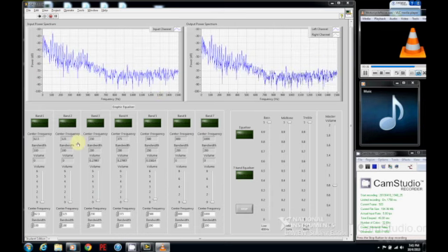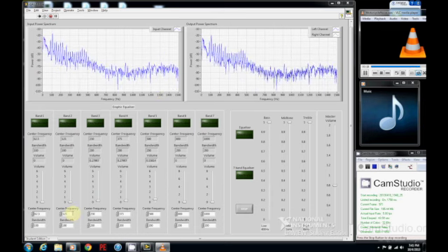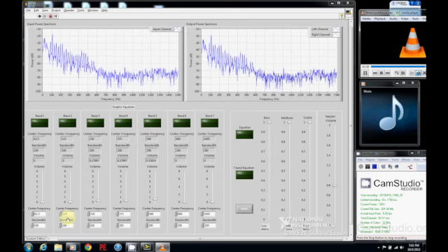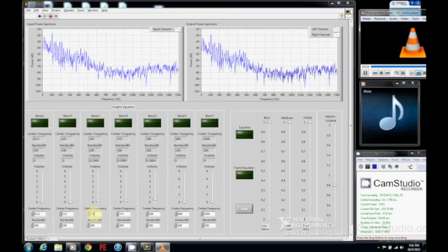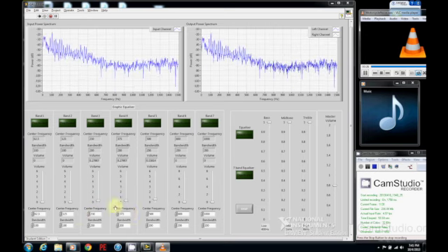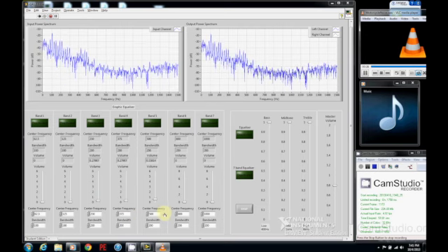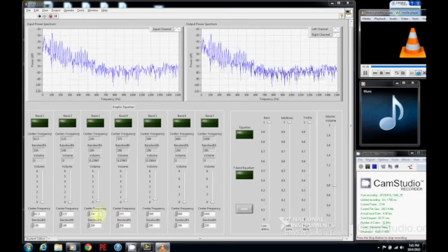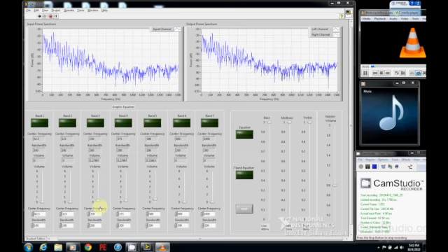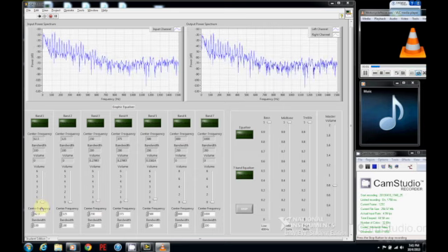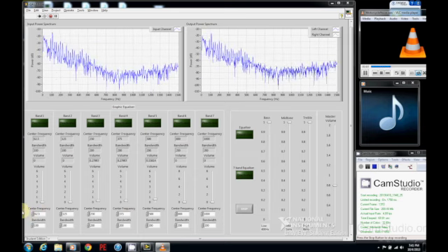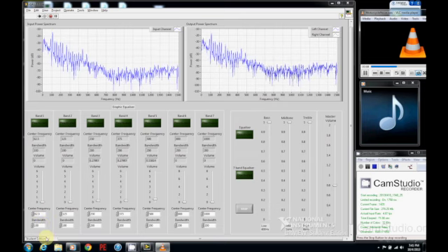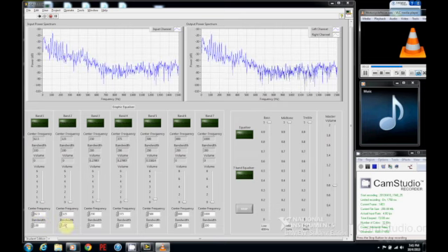Moving on to the filter banks, the first filter was set at a center frequency of 125 Hz, corresponding to the fundamental frequency of the engine noise. Successively, the harmonics at 250 Hz, 375 Hz and 500 Hz, not extending beyond 600 Hz, were also used. On top of that, we also calibrated another band at 62.5 Hz so that we are able to clean out some low vibrational noise. The bandwidths are shown over here and range about 100 to 200 Hz.